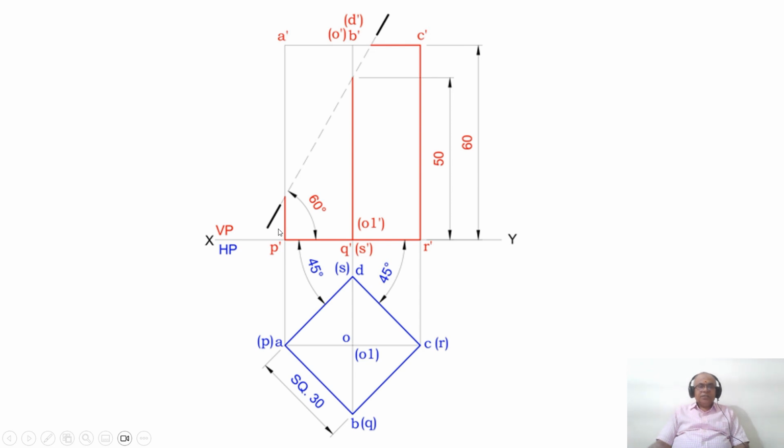Once you do that, you are cutting the prism into two parts such that the section plane is at a height of 50 mm from the base on the axis. Now the section plane is passing through this edge here and the top surface. Once you do that, you darken the remaining portion of the prism on the lower portion.